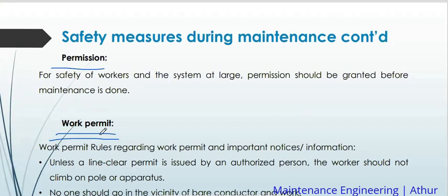When you are going, for instance, to do maintenance at Chumuru on a transformer, he has to go to the power station, switch off, clear the line off, and bring a permit and give it to the person responsible, maybe the senior linesman, to show that there is no power in the line. Then us guys will start working.